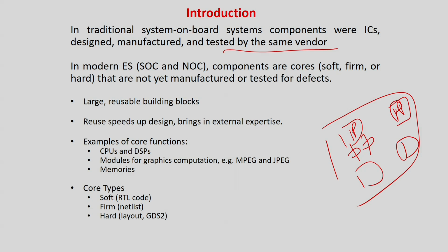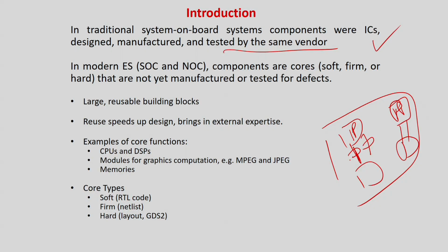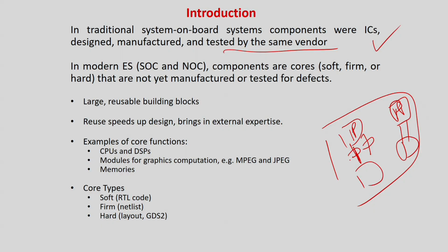But at the traditional level, when you are doing board based design, it was up to us that this pin is very important, I can put an external mux to go for test mode. These pins are not very important, I can take an ad hoc decision, because most of the chips are built by me, or a few I have taken and I am soldering them in a PCB. But in case of a silicon or a die, it has to be manufactured, it has to be fabricated. So, I have to be very careful on what I am doing with the pins. So, there should be a proper protocol for manufacturing these devices, in the case of a chip.